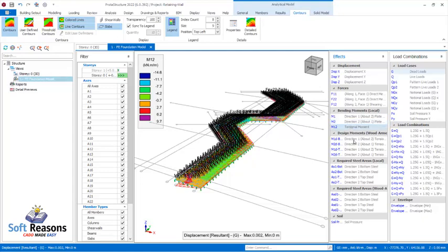Okay, and then the design moment, using Wood and Armer in both bottom and top successfully, and then required steel area. So this is supposed to give us steel area. What you see in here is a steel area of this base. This is 405.38. So this can be checked on the table to determine the diameter of steel that will be used to reinforce the base of this wall successfully.